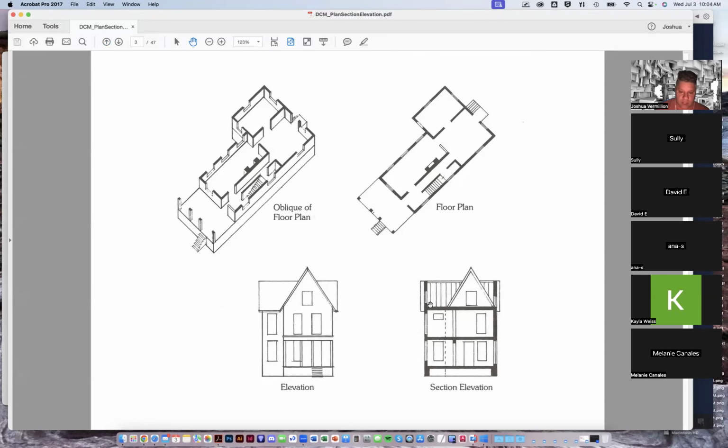And what's really key here is that when we're cutting things, either in plan or in section, we beef up the line weights around the things that are being cut. Oftentimes we'll add a hatch or a poche or a fill because hierarchically we want to see what's being cut through.